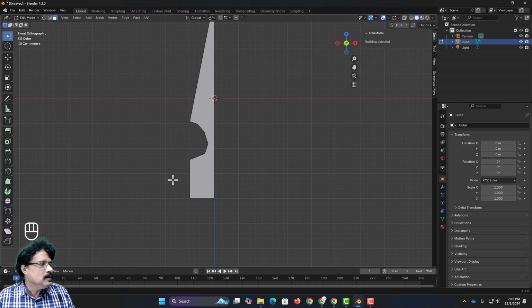Now similar to this, again I will press K into the knife tool, and I am going to click at this point. I am going to press C to enable cut through, and then press X to align it along the X axis. So I will bring it somewhere here, click it, press X twice to come out of that constraint.